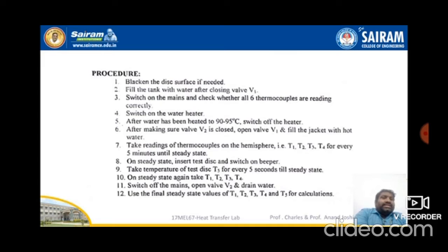Now let us discuss how to conduct this experiment. The first step is to blacken the disk surface if needed. If it is not black, you should make it black by coating some paint or material. It should be black, then only will you get proper results.